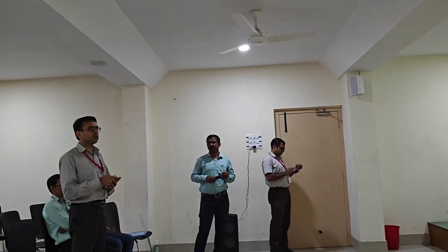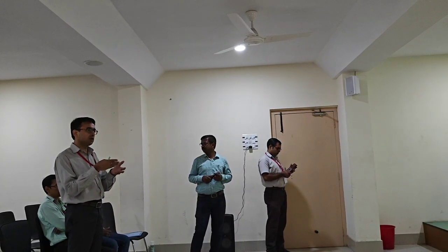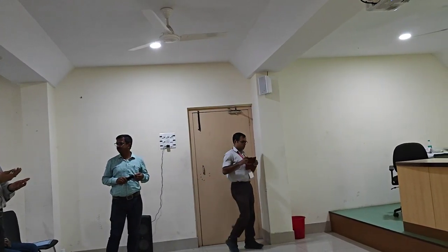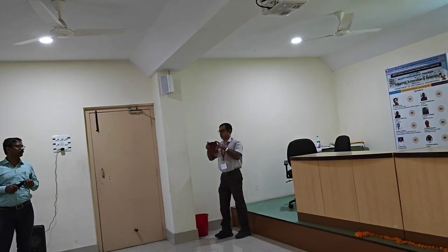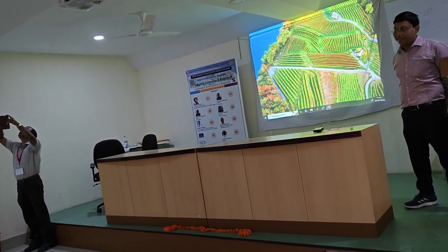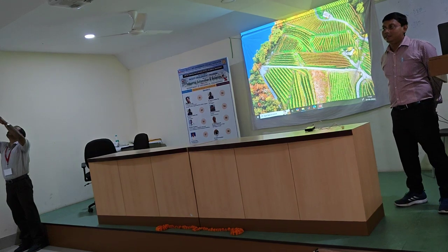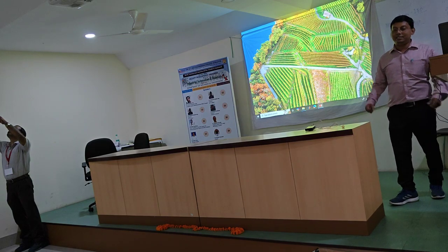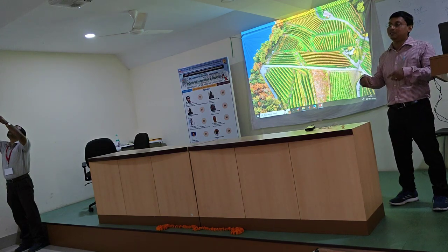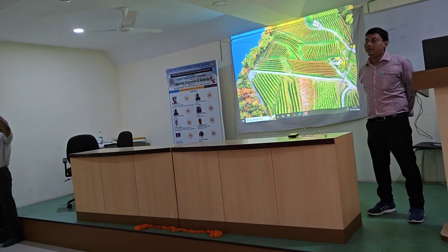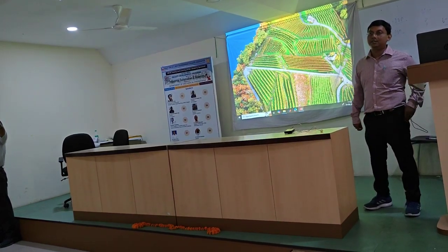In general, say for example, fused deposition modeling. There is an inbuilt parameter like infill amount, infill amount 100%. Suppose I need a product with infill density 100%. There is no porosity, no such honeycomb structure. If there is a honeycomb structure, porosity is not an issue. But if I need a solid component, then the infill has to be full.